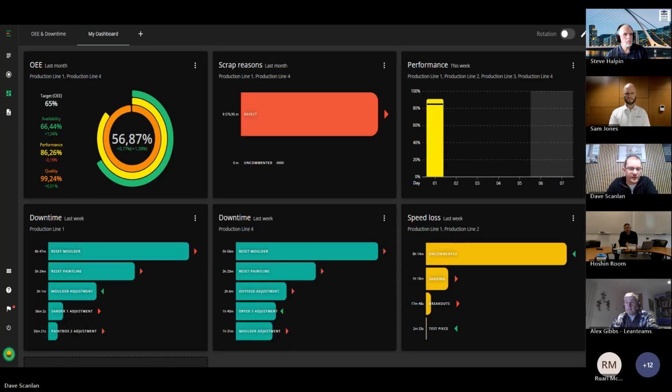So what we did then is I went in just to get 1 month on line 1 and line 4. So again, it's around 56% OEE for a month, which is not exactly where we need to be. We'd like to be at 65% or over. So we went to the downtime again. It was resetting and resetting. The second one is again. So we've huge times on resetting molders, and that's our main loss in a lifetime factory. Main loss is availability. Everything else seems to be okay, but the availability is wrong. It's just not where we need to be, as a high class production factory.